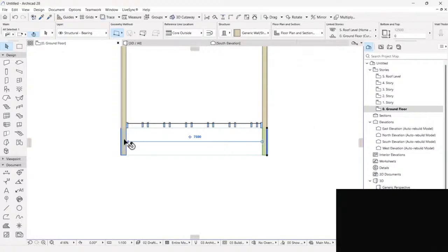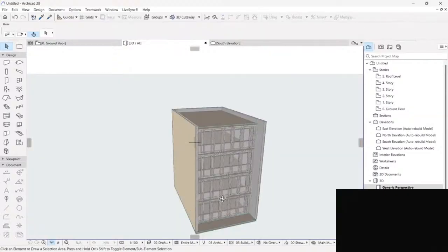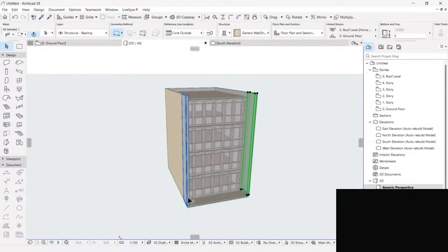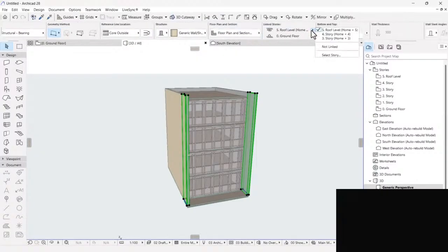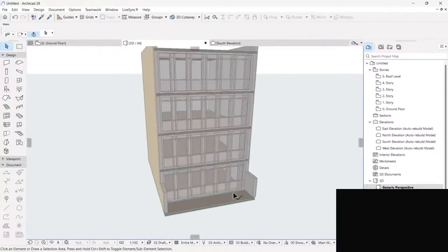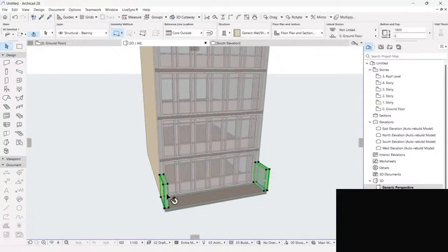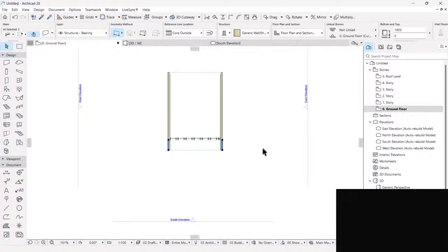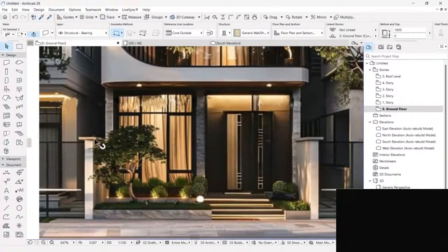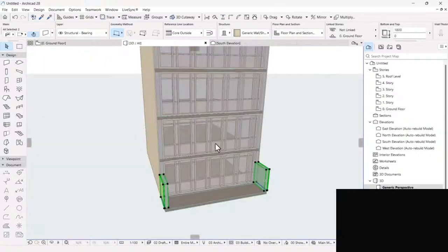So these walls are going to be, if you check on 3D, they should be the height of a boundary wall. So I'm going to not link them and set them to 1.8 height. Perfect. And then you normally have a cap. So if you look at the image, we have this coping at the top of our wall.